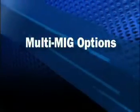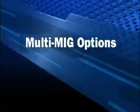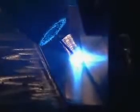Let's discuss each of the available processes and their related benefits. In order to understand pulsing processes, we need to understand the basic principle of GMAWP. Pulsed MIG is a modified spray transfer process. Pulsed transfer continuously propels drops of molten metal across the arc.